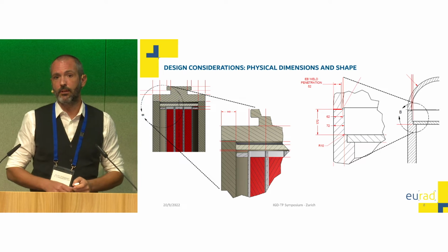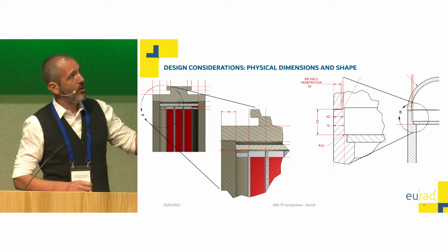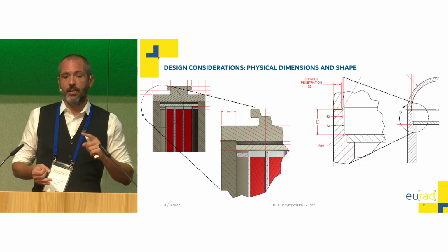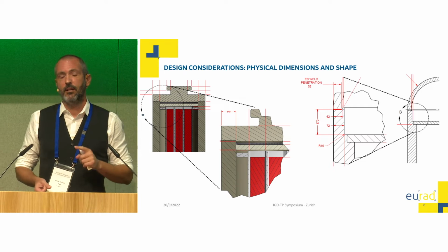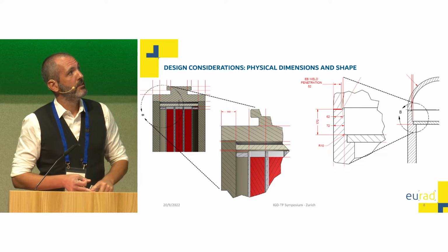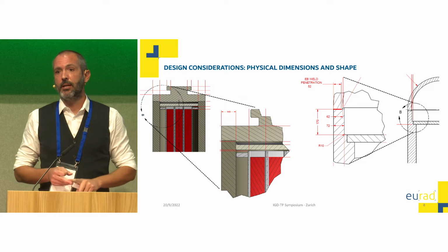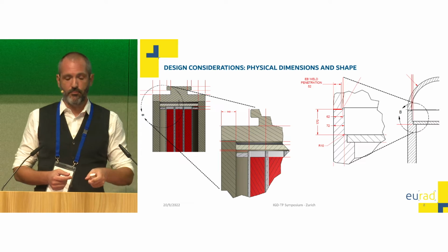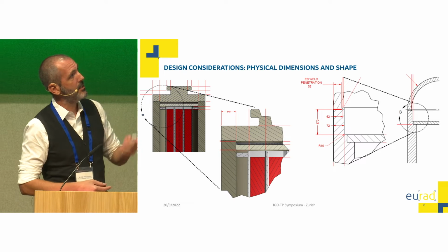Coating or no coating. Obviously, this is much faster to fabricate. It's much easier to inspect, and it has much lower propensity for flaws. So you can make your manufacturing process faster and your canister stronger and more robust, just by changing the lid shape.